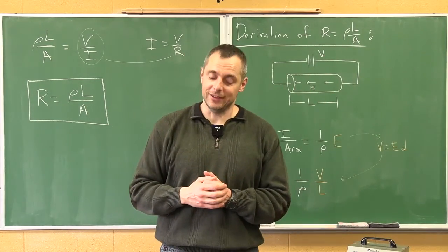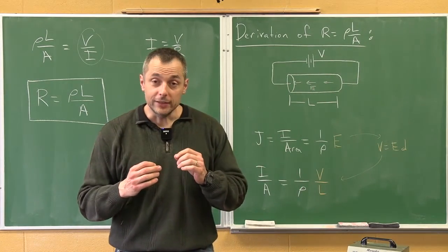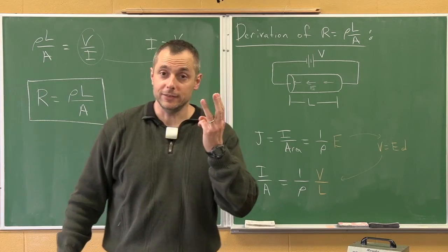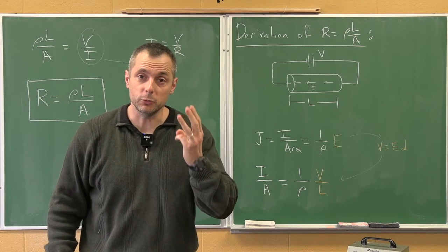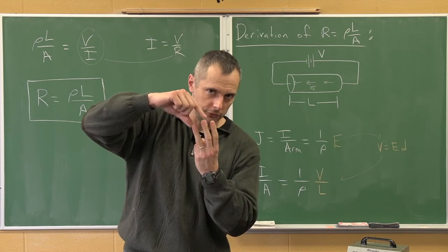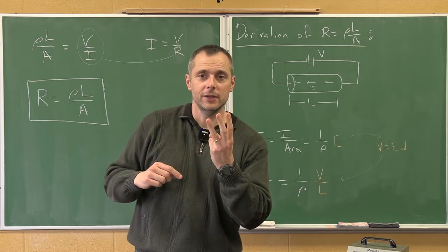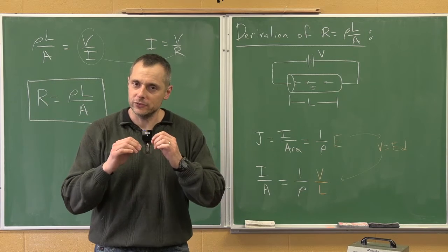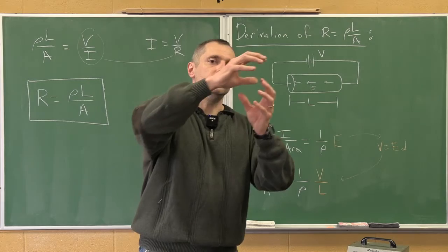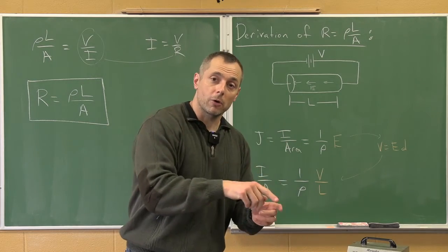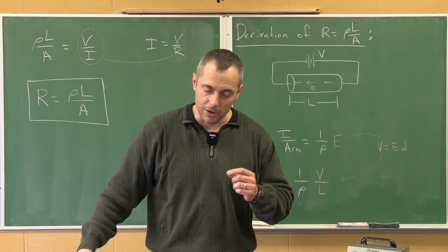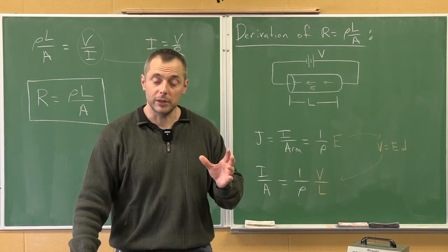So that's it for today. We learned how to calculate the resistance of wires with this expression, and then that completed the 3 basic ingredients in Ohm's law: voltage, current, that was yesterday, and resistance. And they all go together in this very simple, very common sense expression. I equals V over R. More volts, more current, more R, less current. Common sense. All right, so the homework tonight will just be applying these formulas, all algebra-based.